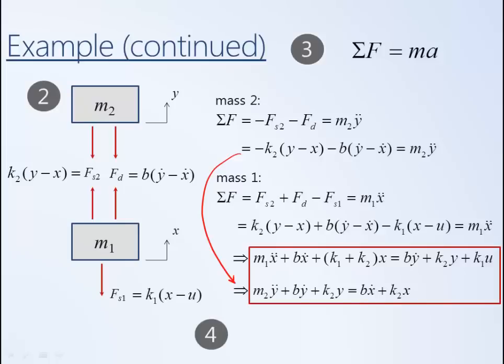The last step in the procedure is to attempt to double check things to make sure that they make physical sense. In general, what you can do is substitute the values for the masses and the stiffness and the damping, and you can see if the behavior makes physical sense, i.e. the rate of decay or the frequency of oscillation, etc. In general, for a physical system like this, a suspension, which is in essence a passive system, it should be stable. The natural response of the system shouldn't blow up,